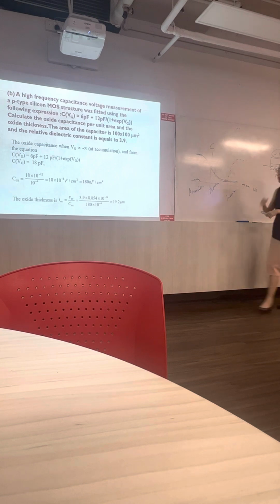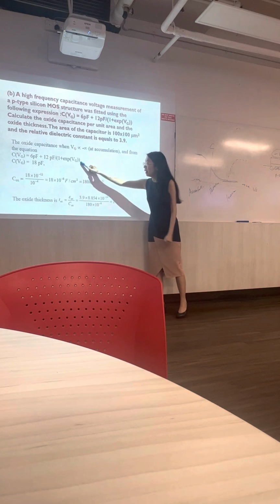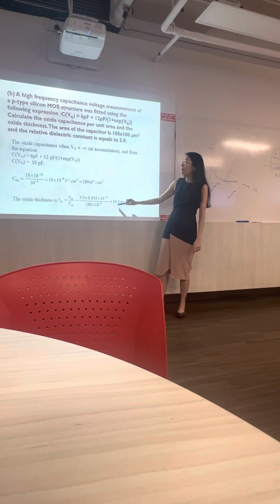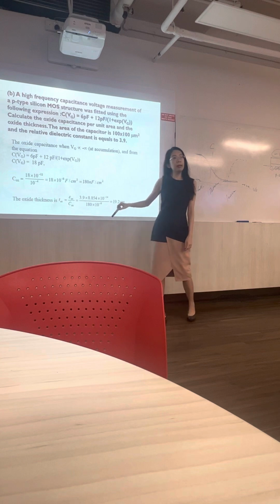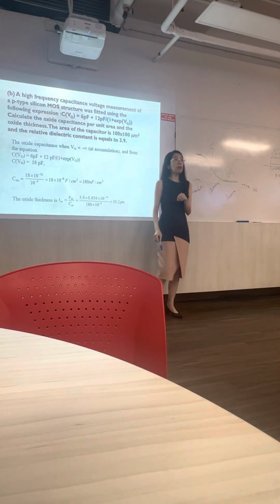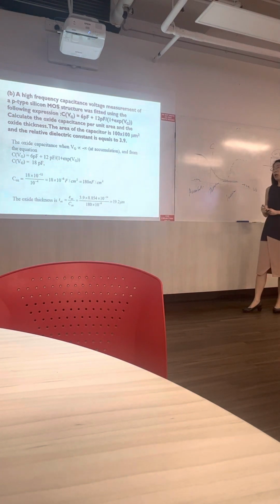Okay, so please calculate and see whether it is correct. It's a theoretical model, so the oxide thickness will be a bit large. The number here is too high, in micron, so it wouldn't be like that actually, right? That means this expression probably needs to be tailored to derive a better oxide thickness.